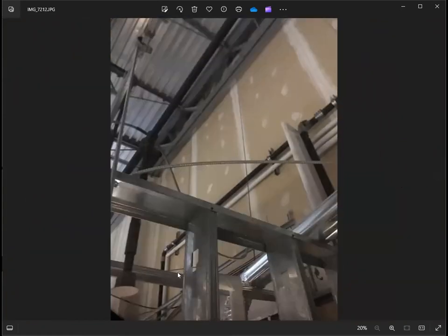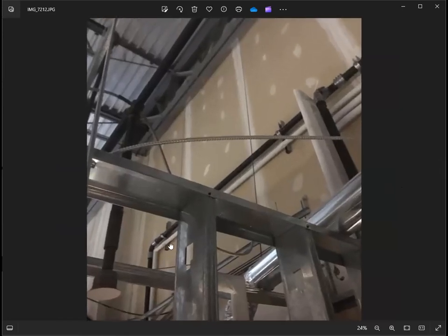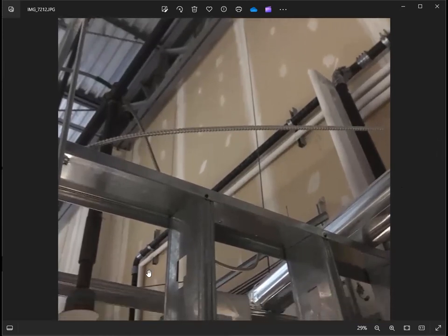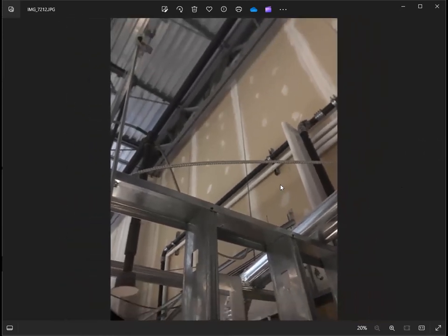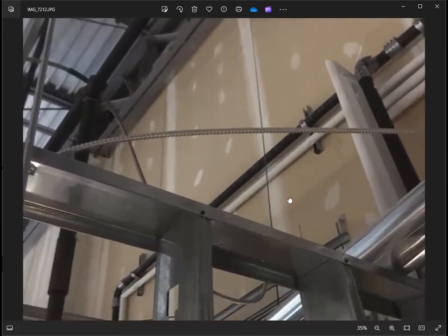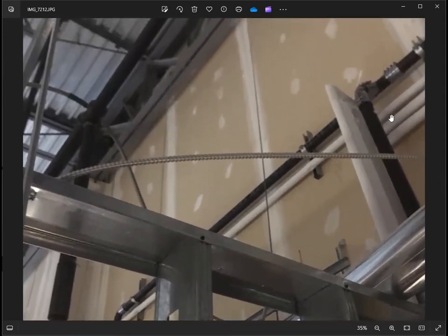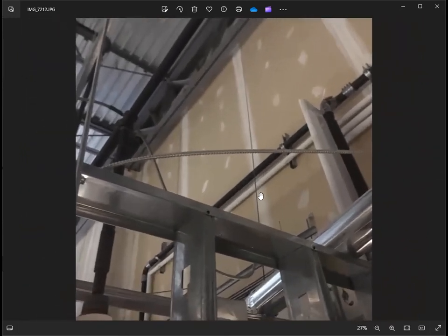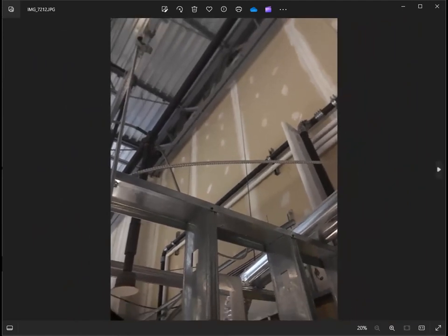And right here, I'll show you. I took a photo because of the new piping, domestic piping insulation. This is a good opportunity to take a photo while the ceiling is not covered. The drop ceiling tile is not installed. So you can see here all the copper piping for the domestic water is insulated. So that's under energy inspection too for the insulation.